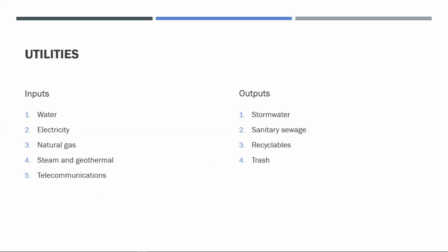Another thing is that a survey of existing site utilities also typically includes the location of utility poles, overhead power lines, fire hydrants if there are any, and utility boxes, electric or electronic transformers and such. Information about the capacity of each system is usually also provided.